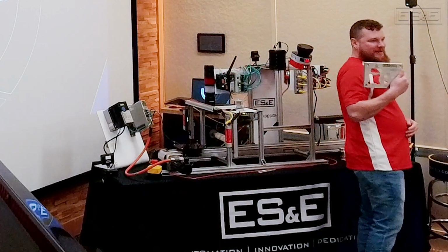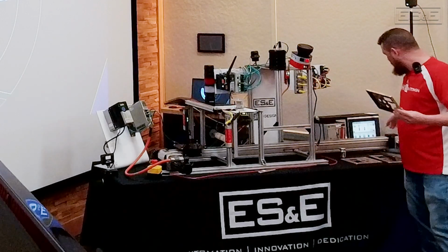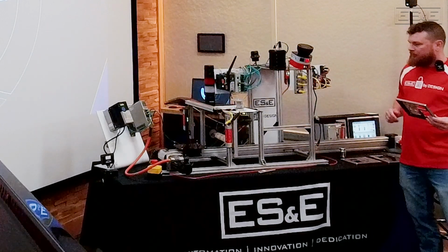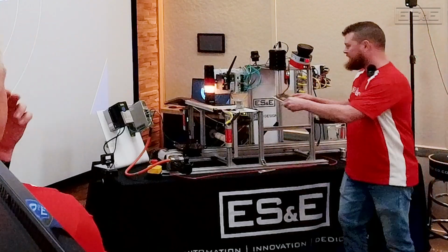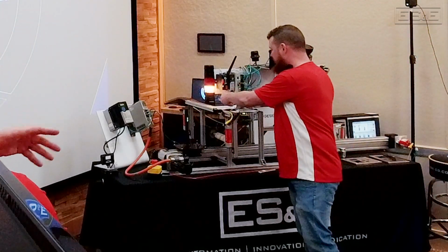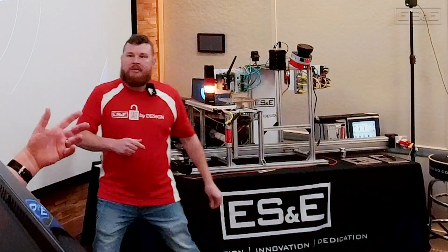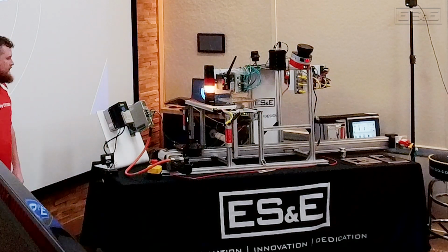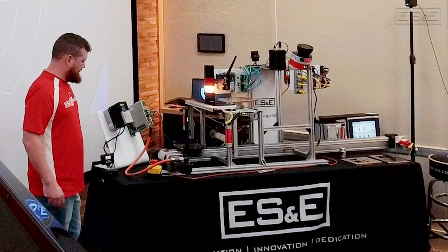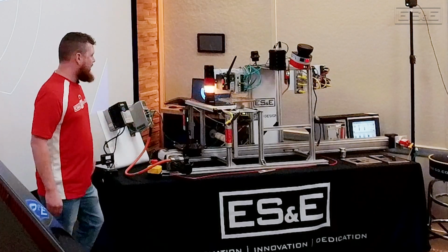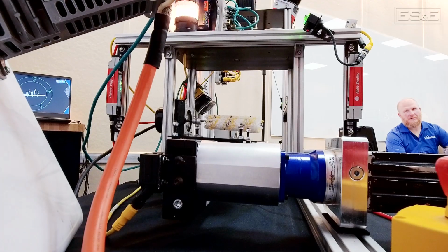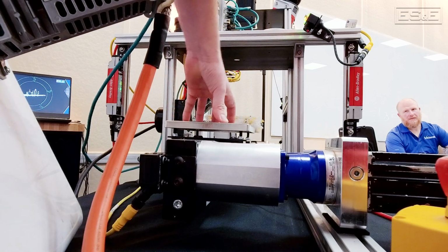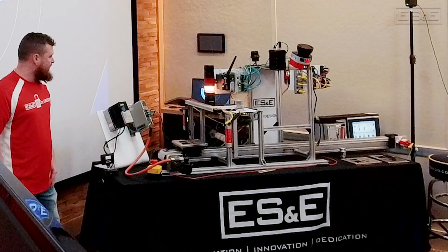So again, we've got our correct part now. The operator will come over again and initiate this weight check enable. We'll be prompted again to load the part on the scale. Robbie, could we just have that work, and we don't have to start it every time from the HMI? That is correct. The weight check is good. We're prompted now to move it from the scale to the trolley. We'll make sure manually that it's on there correctly.